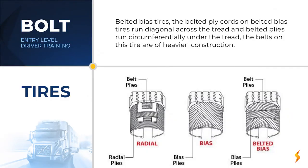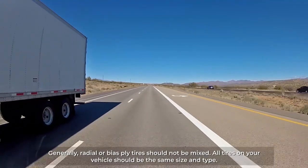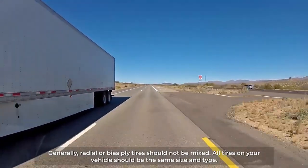Belted bias tires. The body ply cords on belted bias tires run diagonal across the tread, and belted plies run circumferentially around the tire under the tread. The belts on this tire are of heavier construction. Generally, radial and bias ply tires should not be mixed. All tires on your vehicle should be the same size and type.